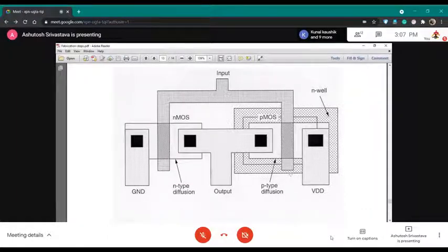NOR gate is made up of 4 transistors. So all you need to do is to get number of gates, you just need to divide it by 2 or 4. So you will get a rough idea. So once we are talking about billions of transistors, just 1/2 or 1/4 of it are the number of gates that are there inside your chip.